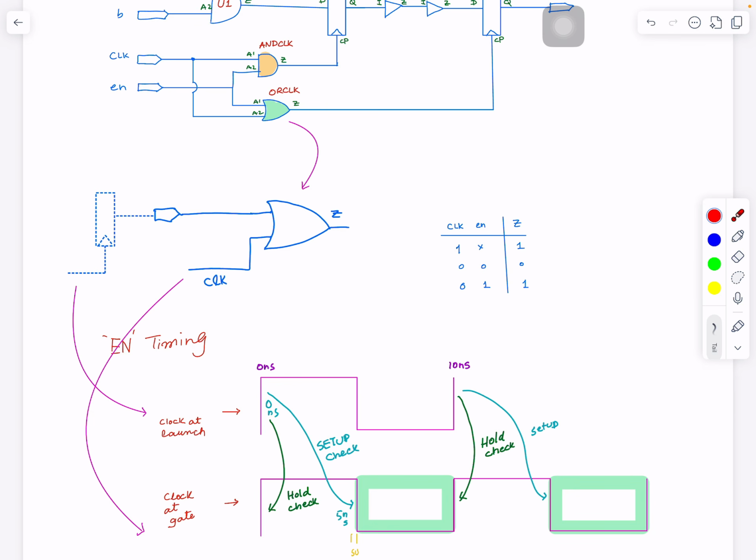This is our virtual clock, and this capture clock is here. Make sense? So for a timing path, we define clock here, we define clock here in our timing constraints. It's just like a stimulus. You need to tell the tool what the clock period is. For example, here I'm saying it's a 10 nanosecond time period, which means its frequency is 100 megahertz.